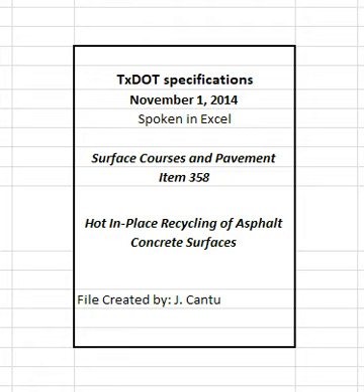Unless otherwise shown on the plans, obtain 2 6-inch diameter cores side by side at each location selected by the engineer for in-place air void determination. Mark the cores for identification, measure, and record the untrimmed core height, and provide the information to the engineer. The engineer will witness the coring operation and measurement of the core thickness.